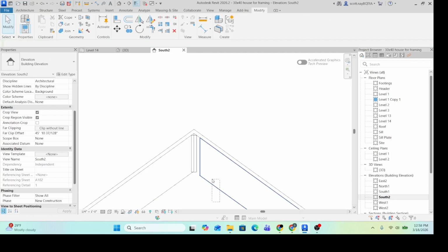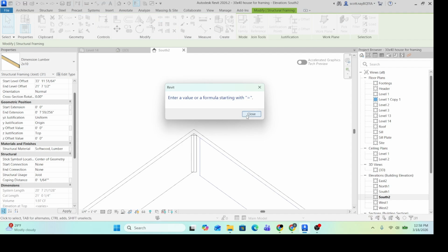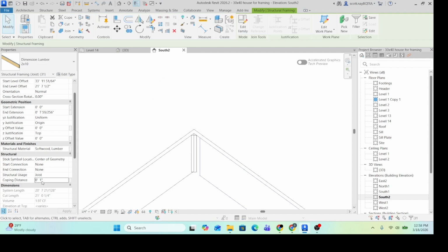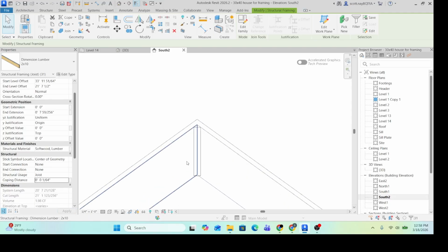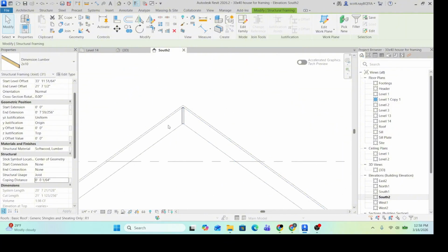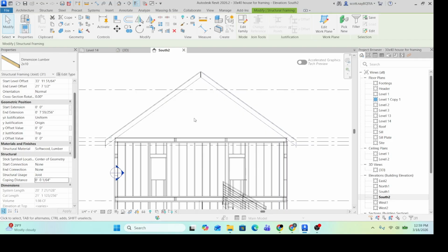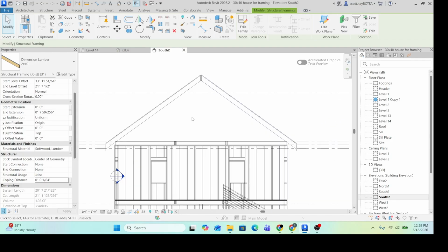So I'm going to do a right click, come in. Right now they're all at 1 inch. I'm going to make them all 1/64 of an inch. I doubled up on the inch. So now instead of cutting in, all of them come right here. So you do the same for the other side. That would be your roof. I'm going to go ahead and stop the video here. I'll come back and show what to do with this gable end in just a minute.